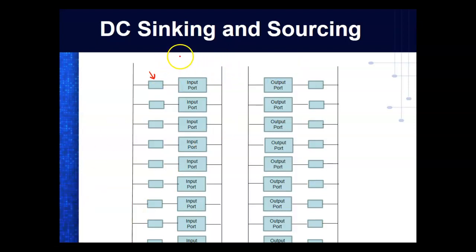So on this one, the negative would have to be connected here, and the positive would be connected there. Then this right here would have to go right there, and this right here would have to go over here on our single power supply. So I had ours connected backwards. This is the way our PLC is actually wired, but I had to jump them.